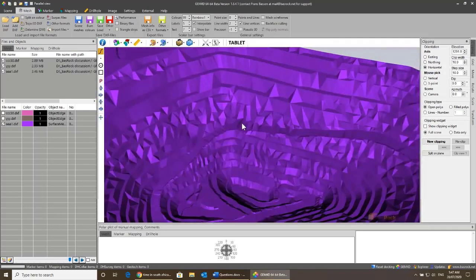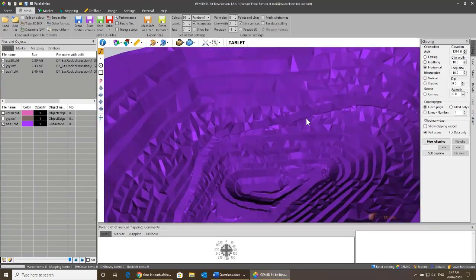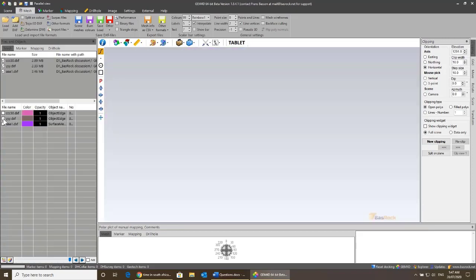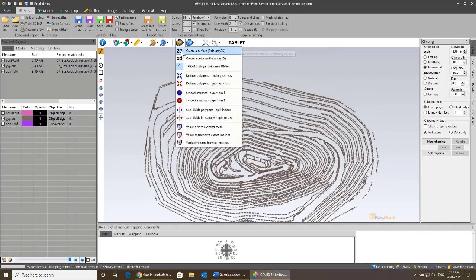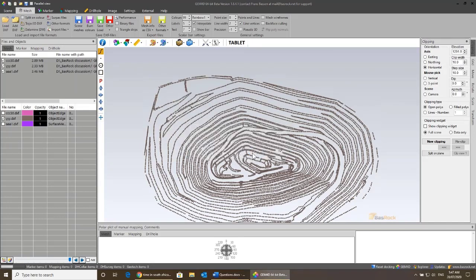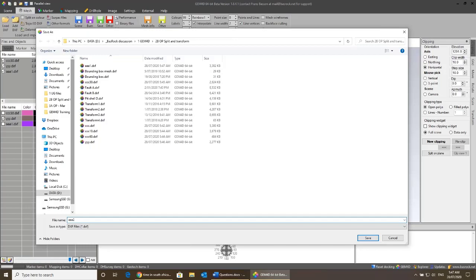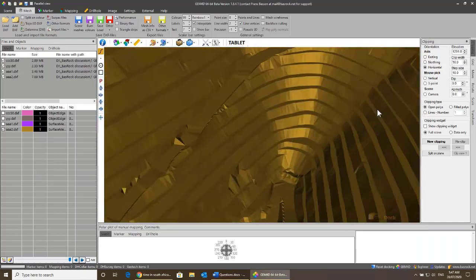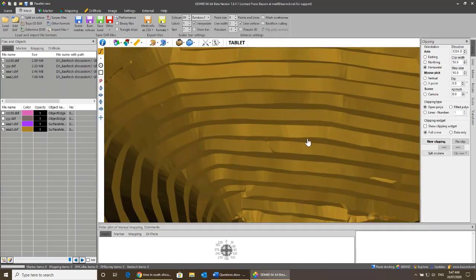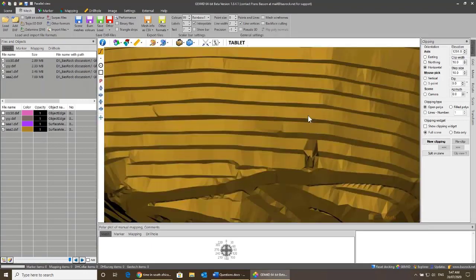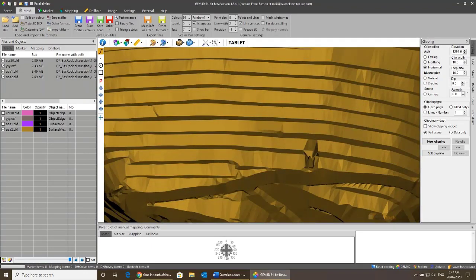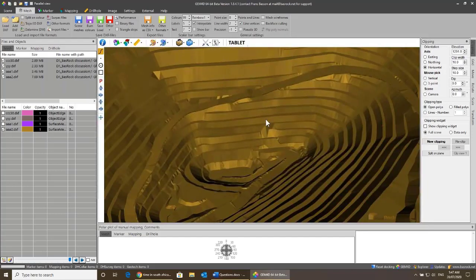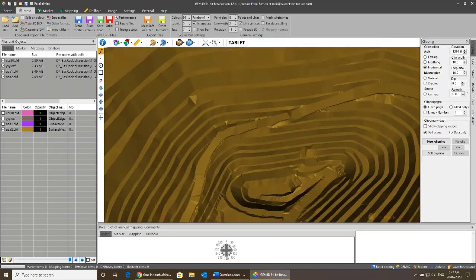So that's quite messy. You can see there's a whole bunch of these irregularities on your mesh. So let's use the second one. Type same, yes. And I'll call it AAA2. And now you see you get a far cleaner surface to what you had on the original one. So this is very, very close to the original data set that you had. There's some things that messed up, like this portion over there, but the majority of the surface is actually quite good. There's some mistakes. You can then subdivide it even further if you want to have a more accurate result. But I think the idea is clear.